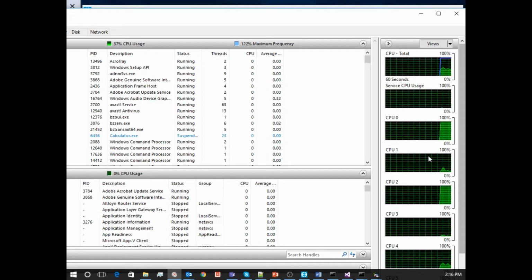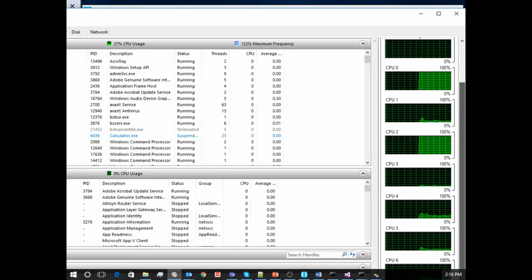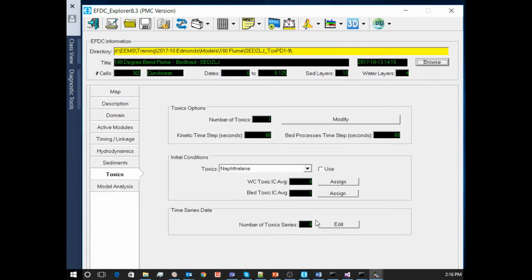You can see that I turned on 2 cores, and so I've got these 2 threads being 100% utilized, which means that this physical core and this core are being used. But down here, I still have available space. So I'm going to run the other run on those 2 cores.